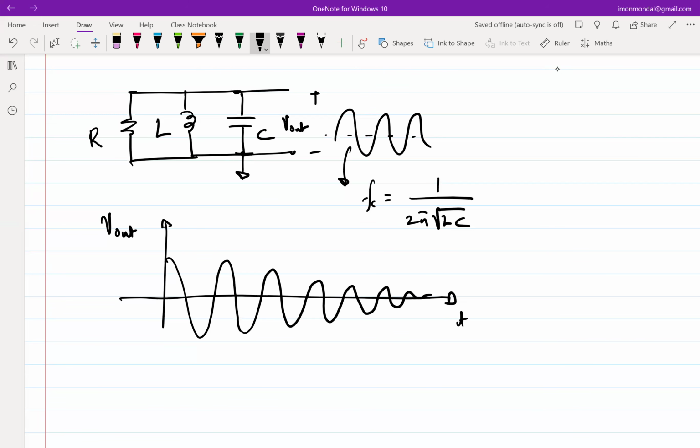Okay, fine. So let's say there is no frequency change, there is a damping. And this damping will happen, and eventually everything will go to zero. So what is the fix to this? The obvious fix is to say that if I can only design a circuit which can cancel that effect of R, so essentially, if I can append something here which can give me a negative resistance.